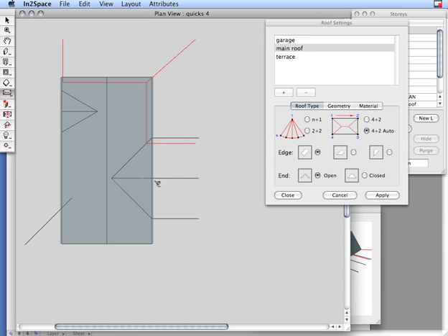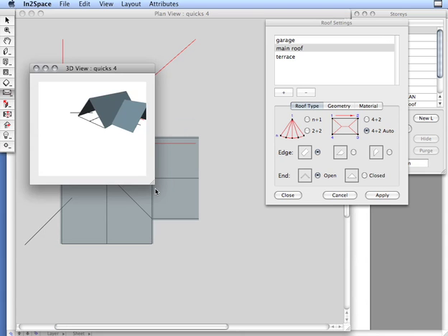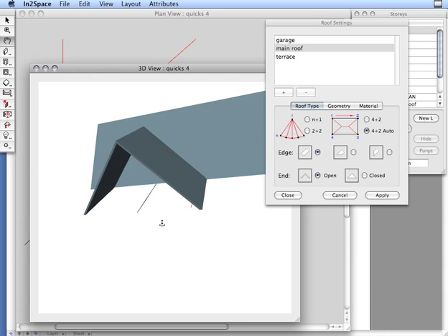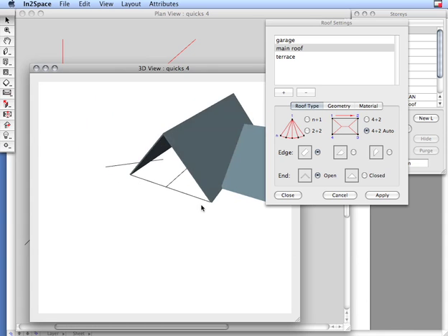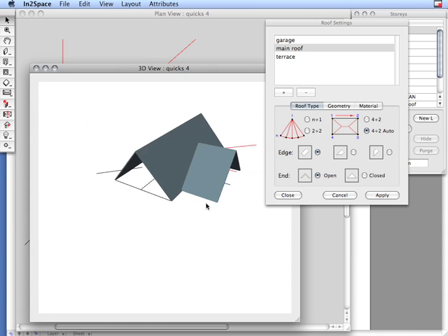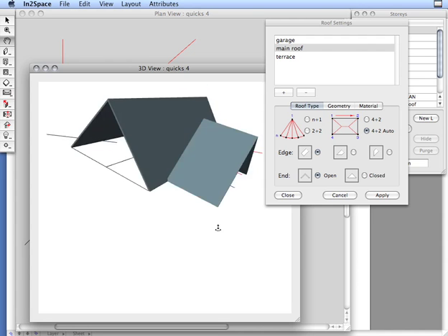Same principle. Again, the apex this time is going west to east, so there's our first point, second point, apex will be drawn in this direction, and third and fourth point. And there we have a simply constructed roof. We put a thickness on there, you can see edge to edge. You can have 0 thickness and build up the drawing using extrusions.